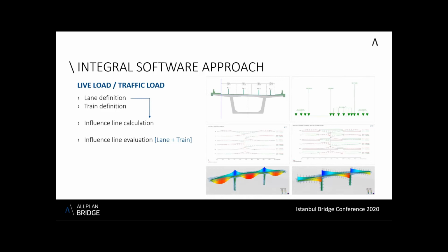For getting the worst influence of traffic loading on a certain lane, load patterns, also called load trains, are required by the design code and are automatically placed along the lane in the relevant position. The extreme values resulting from different load trains and on different lanes of a lane set are superimposed. Combining this result of different possible lane sets gives the final traffic load envelope containing the relevant extreme values.